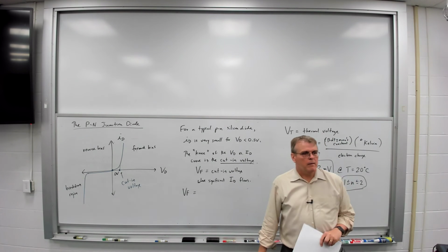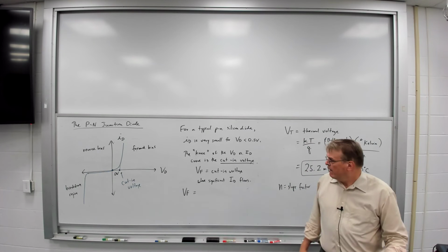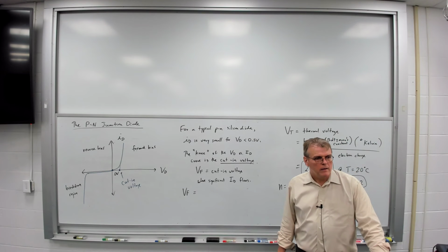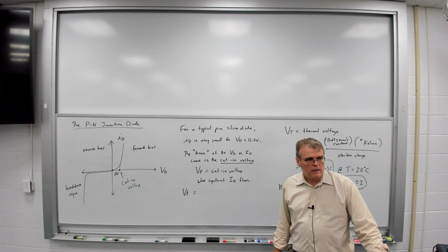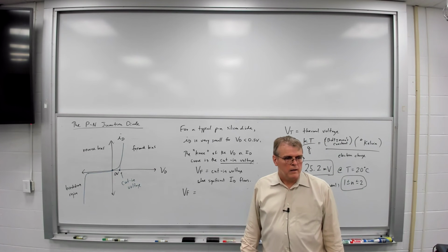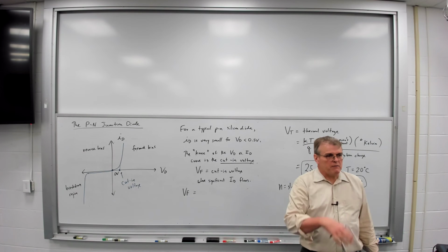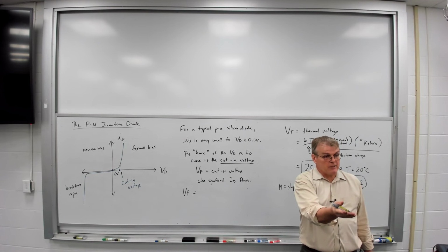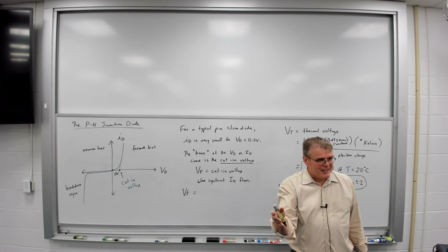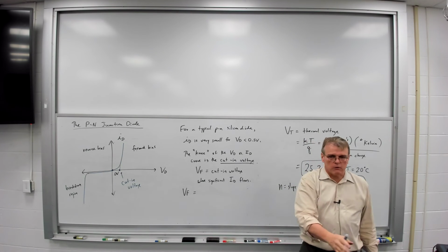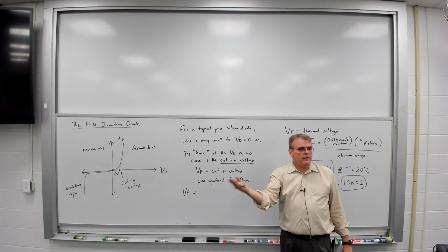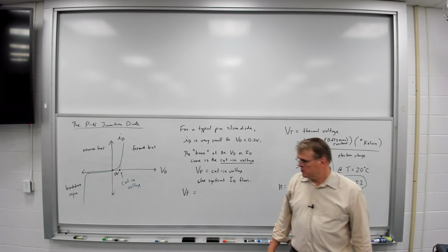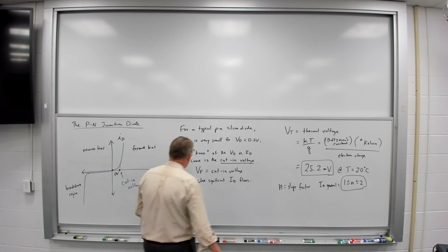Yeah? I have a question about the whole decade system that we just saw with 57.6. Does it go both ways? So if you divide by 10, would it be minus 57.6? That's correct. If you took a current and divided it by 10, as long as you're still in forward bias, then yes, you're going to see that the voltage reduces. So it goes both ways, decade increase or decrease. All right? So yes, you're correct, both ways.